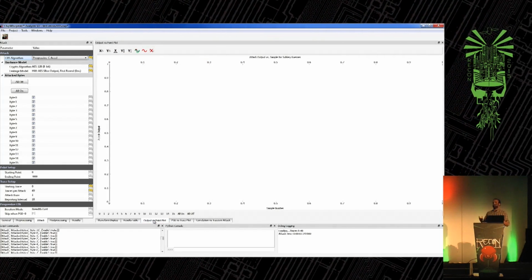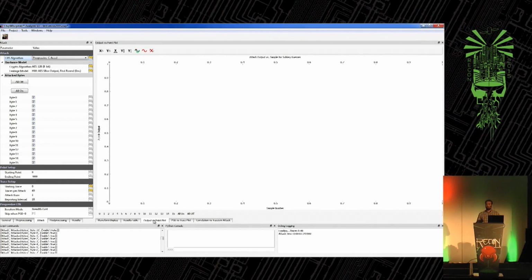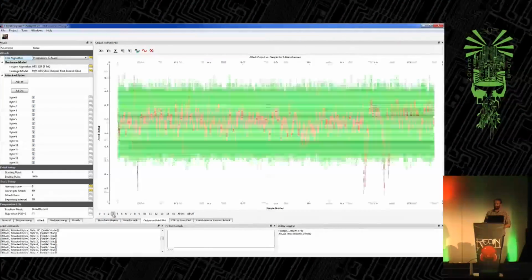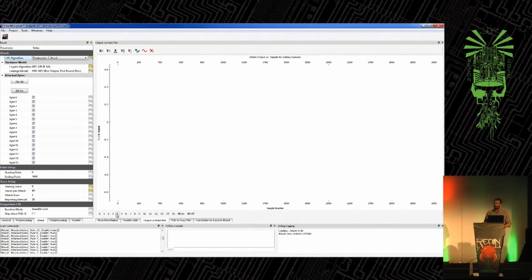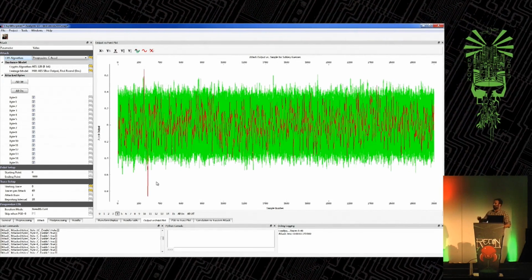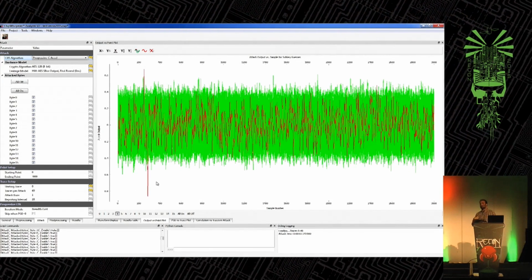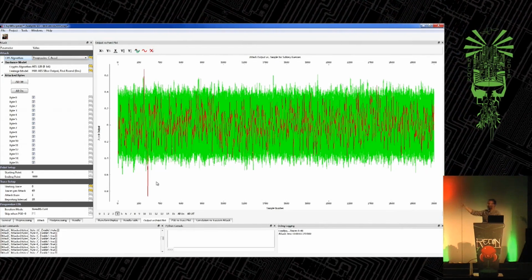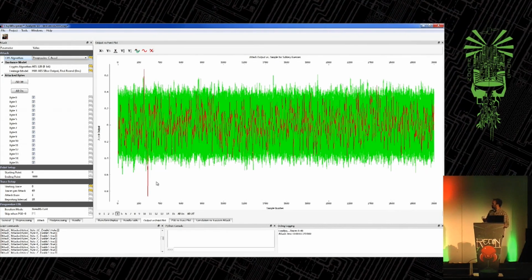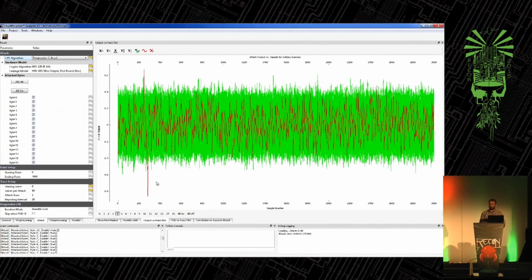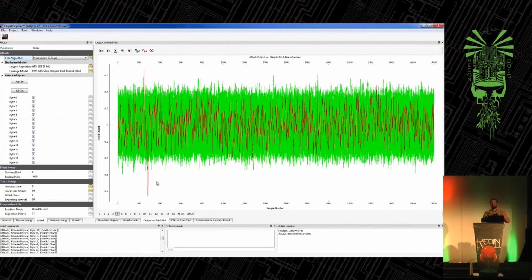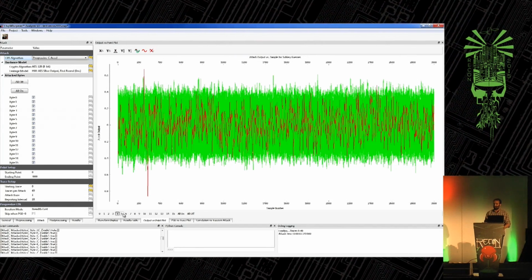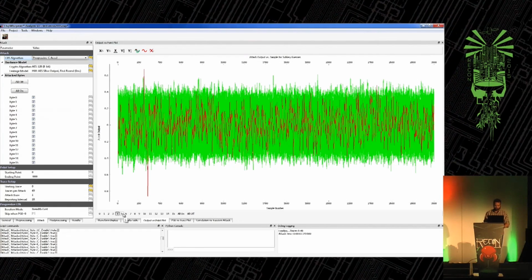One of the other questions people always ask is, how do you know where the encryption is happening? And the analysis itself gives you some of those answers. What this is graphing is the correlation; it looks for that linear relationship. And this peak is at various points in time as it's executing instructions. All I do is send you data, and at some point between sending you data and getting data back, you're running the encryption algorithm and doing that operation I'm targeting.